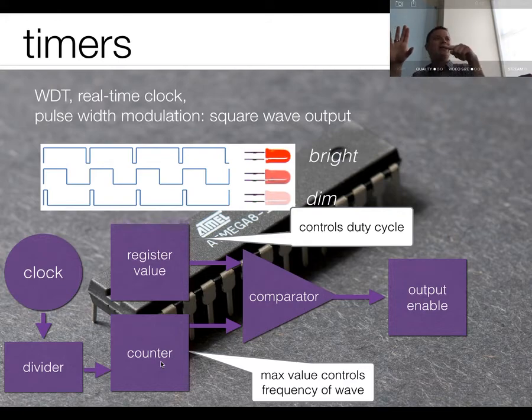then I want to divide down the clock that I put into it. Otherwise, it's counting up at 16 megahertz, 0 to 255, and this pulse width is just going crazy. It may not even be detectable by some of the circuitry that we have. If we divide that down to 1 kilohertz, then it's going to count from 0 to 255, and each of those, it's going to count up at 1 millisecond. Every 1 millisecond, it'll increment the counter. And so we get these nice pulse widths to come out. All right?